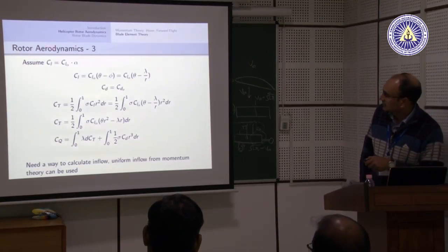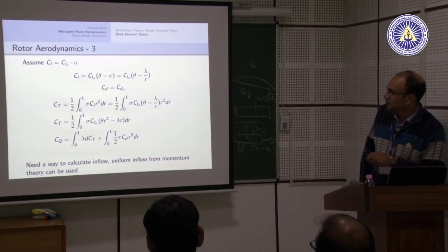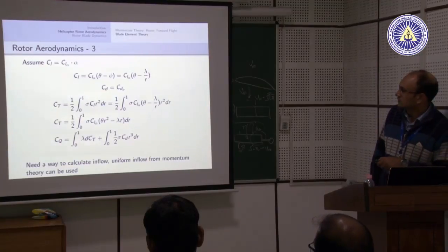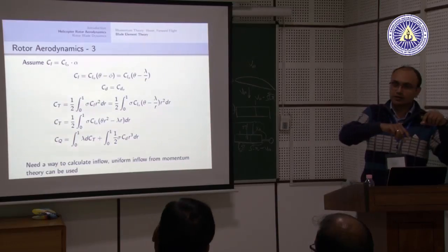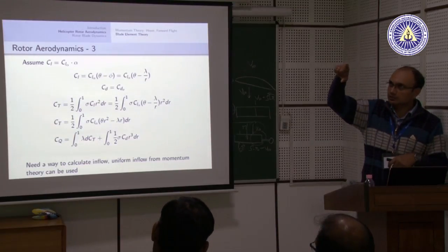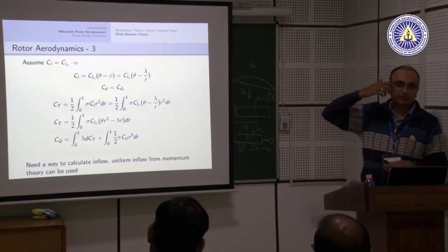To get that, okay, CL. I said, if I know my airfoil, I can approximate it to be CL alpha into alpha. This is the most common approximation which is done. So, this CL alpha is my lift curve slope. Normally the lift of any airfoil increases, then becomes constant, and then it will drop. The drop signifies something called stall.